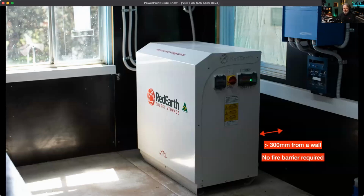Now, the picture just shows you there's outdoors behind, and this is a shed, so it wouldn't apply. But if there was a habitable room on the other side of that wall, I wouldn't need a fire barrier because I'm 300 mils away from it. And that kind of gives an advantage to a freestanding system.